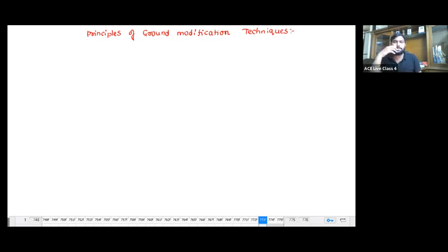For example, you know quicksand and liquefaction, right? Liquefaction and quicksand occur in the case of fine sands and silts. But do you think wherever there are fine sands and silts, there is going to be quicksand and liquefaction? Tell me, I want answers from you. Do you think every time there is liquefaction and quicksand condition? No.